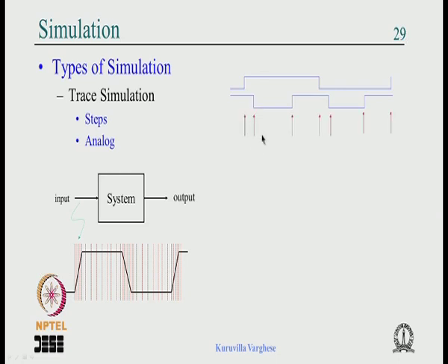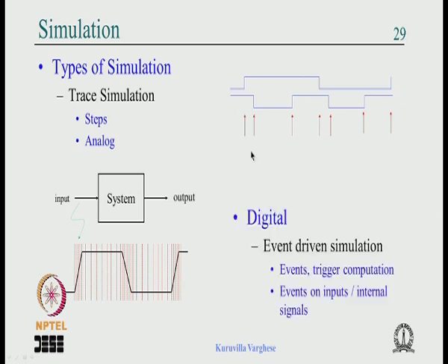So the simulator needs to do the computation only when the signal changes, and that is called event driven simulation. A new event will trigger the computation.